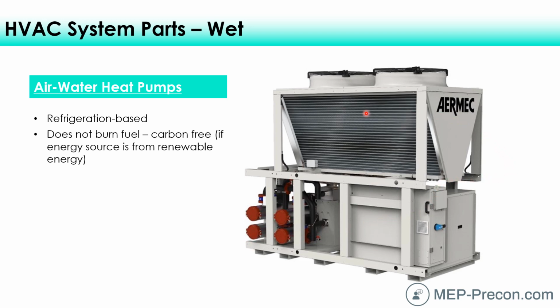It uses the refrigeration cycle and electricity basically to pull heat from the ambient air outside, through the efficient means of the refrigeration cycle. It pumps that heat into the hydronic loop, basically into the water. So there's some heat exchangers within here. This air to water heat pump takes the heat from the air, brings that air within a heat exchanger through the refrigeration cycle, and it's going to pump out hot water.